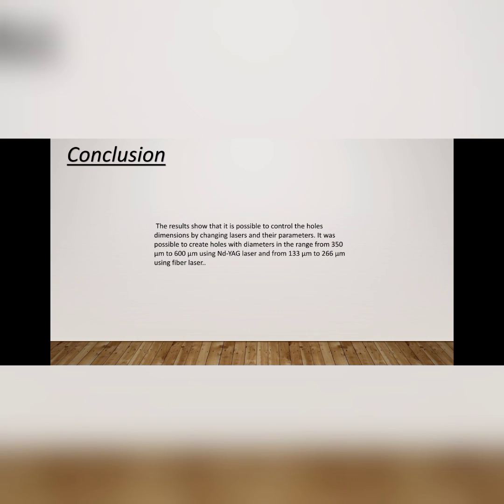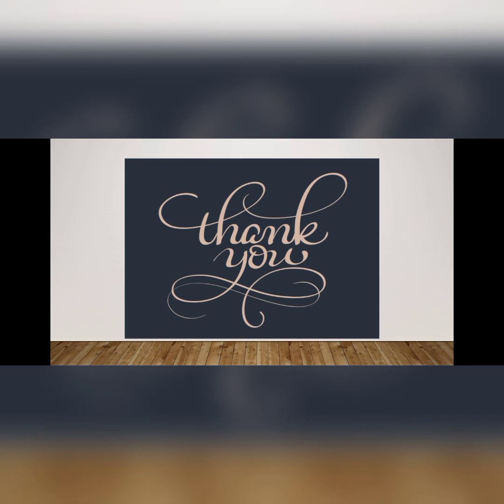And finally we conclude that the results show that it is possible to control hole dimensions by laser parameters. It was possible to create holes with diameters in the range from 350 micrometers to 600 micrometers.